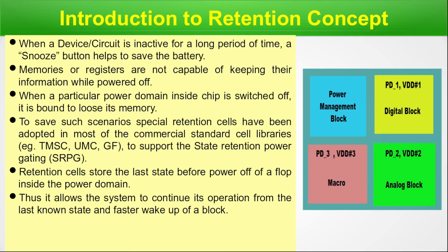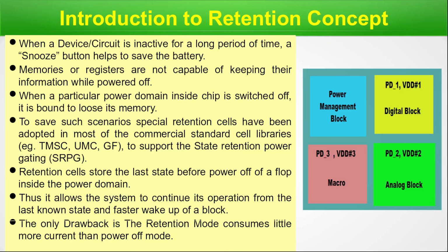Thus, it allows the system to continue its operation from the last known state and gives a faster wake up of a block, because this is a step mostly found in handheld devices where one particular power domain is switched off while it is inactive, and once it wakes up, it can pick up values from the last known state very fast from the retention cells, and this way the device can operate very fast. The only drawback is that the retention mode consumes a little more current than the powered off mode. So we have gone through the introduction and we are done with this particular slide. Let's move on to the next slide.